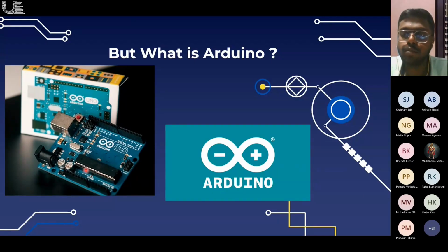The microprocessor is the brain of the computer. Microprocessors are integrated circuits which process the instructions from a computer program, perform calculations, and send data to and from memory and disk. A microcontroller is a specific type of microprocessor. It differs from a normal microprocessor in the following ways. It has built-in input-output capabilities. The microprocessor does not come with inbuilt input-output capabilities. It has to be arranged with different dedicated input and output capabilities. But a microcontroller, with the help of its input and output pins, comes predefined and pre-built with input-output capabilities. It can read and write digital and analog values and states, and can connect directly to the real world.